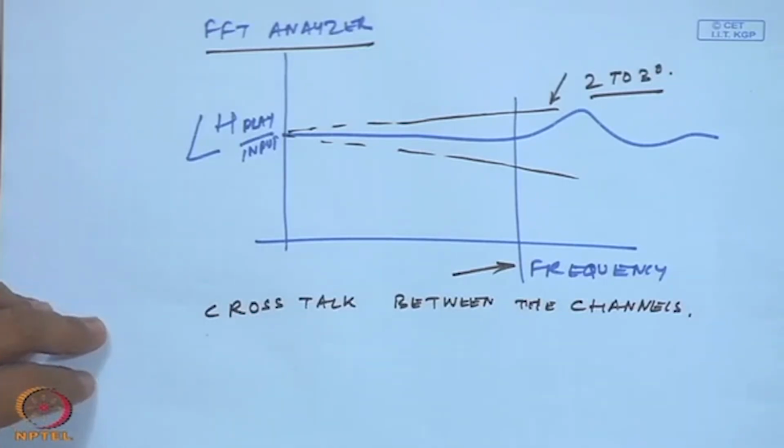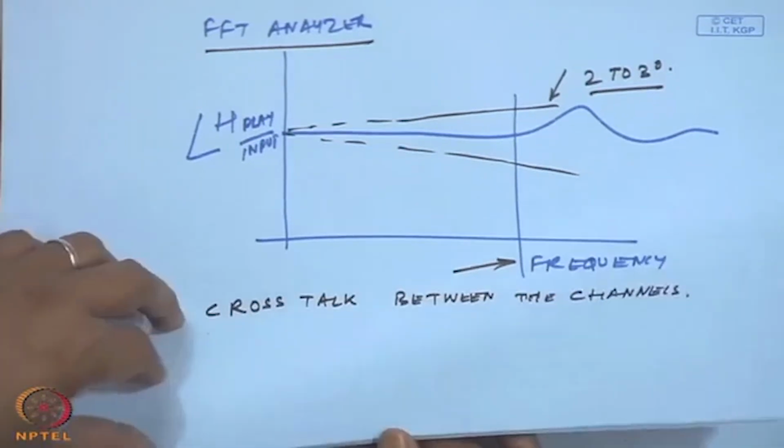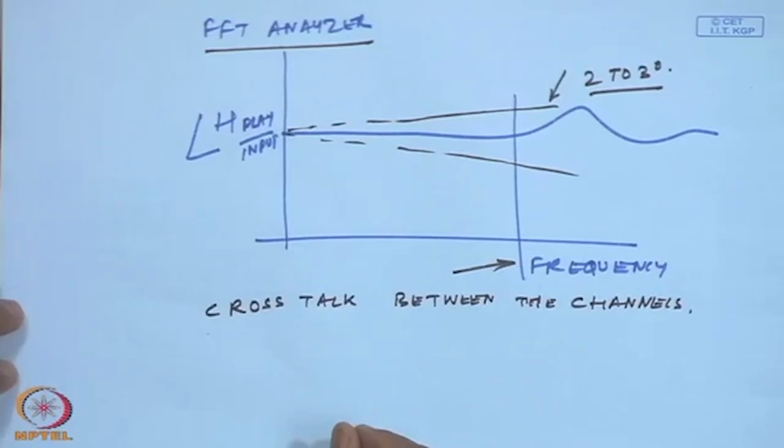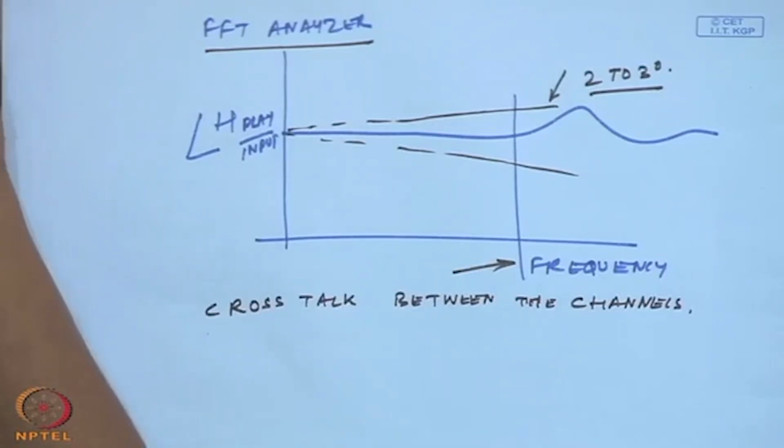Now, once we have recorded this signal, we also need to transfer the signals, and usually the signal transmission rate depends on the number of channels multiplied by the acquisition rate and the resolution. So the data transfer rate is given in bits per second, the acquisition rate in samples per second, and the resolution in bits per sample.